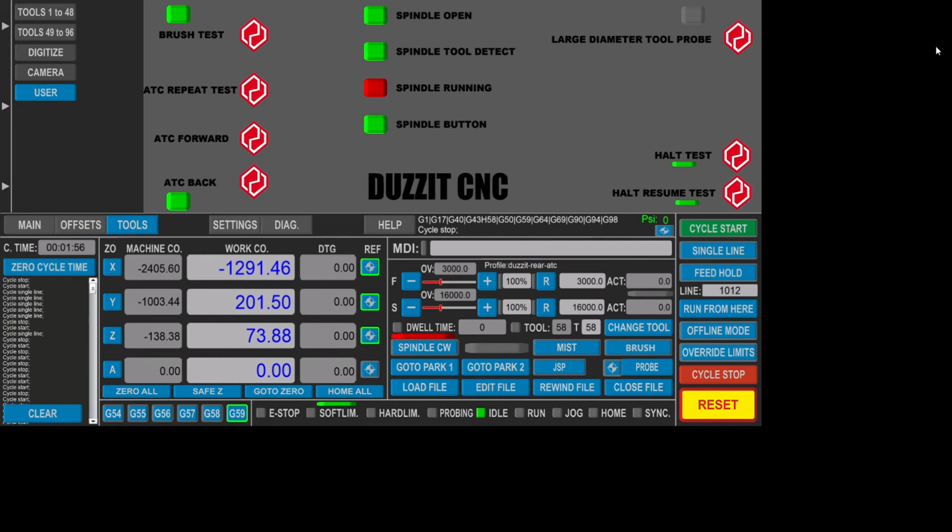This would only be a very occasional use thing, just for instance, if you put a new spoil board cutter in, then you'd use the large diameter probe. A spoil board cutter is normally 50 or 63mm, and that takes you into the routine for just large diameter probing. For all other probing, normal tools would just be this button here.